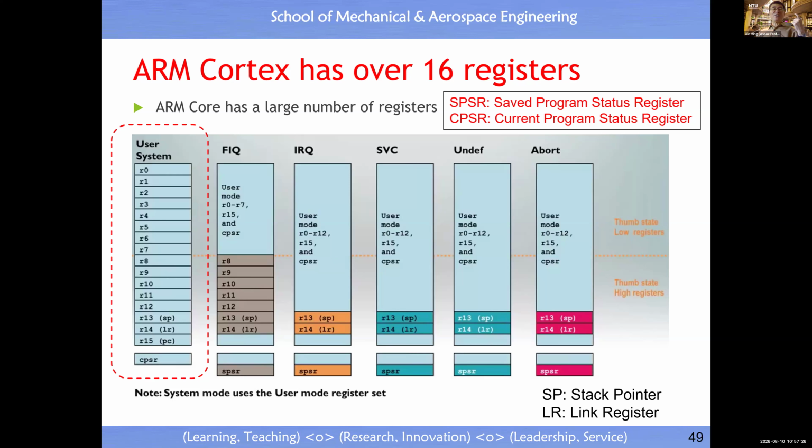Once you retrieve one instruction from the PC register, this value will increment by 1. When you increment by 1, it means what? It points to the next instruction. Okay, that means now we undertake the current instruction, and the PC already points to the next instruction. Then we repeat this operation, and the whole program will be automatically performed by the hardware. Okay, so you understand what a PC is, then you know how the program is executed step by step. This is also something new to you. Just remember it like this. Okay, conceptually very simple.